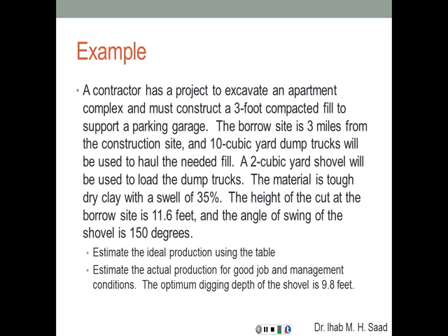Let's look at an example again to make things much clearer. A contractor has a project to excavate an apartment complex and must construct a 3-foot compacted fill to support a parking garage. The borrow site, where you're going to get your soil, is 3 miles from the construction site. 10 cubic yard dump trucks will be used to haul the needed fill. A 2 cubic yard shovel will be used to load the dump trucks. So how many cycles is it going to take for the shovel to fill the truck? This is 2 cubic yards, this is 10 cubic yards, so we're talking about 5 cycles to fill one truck.